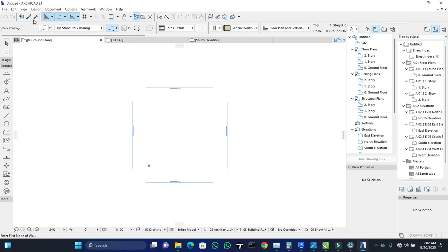So Archicad picks up those parameters, all the settings you've done for that object. And then logically you can assume what the next icon will be. The next icon is Inject Parameters. So when you've picked up parameters from a particular object or element that you finished setting, you can inject those parameters into another new element, or any other element that you feel should be the same as the one you picked up the parameters from.